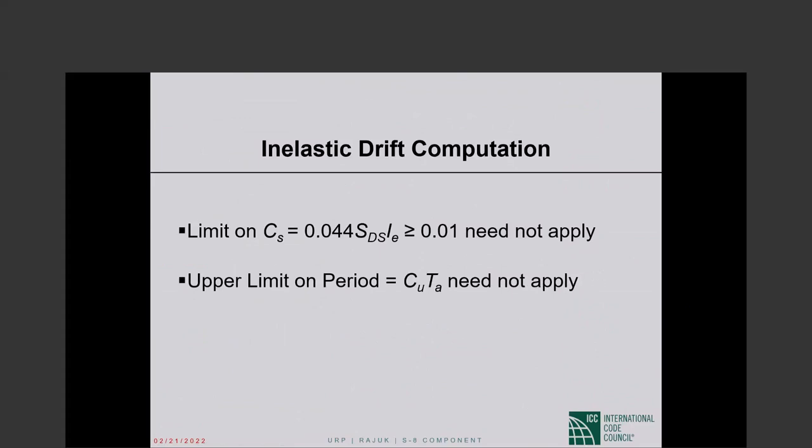Now, something important that I did not mention in the past, or maybe two things. Remember, in the design base shear equation, irrespective of seismic design category, the design base shear may not be any less than 0.44 S sub DS times I times W, or the design base shear coefficient cannot be any less than 0.44 S sub DS times I.